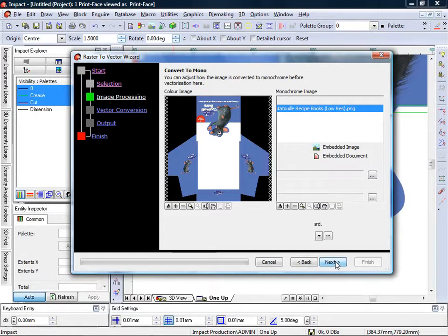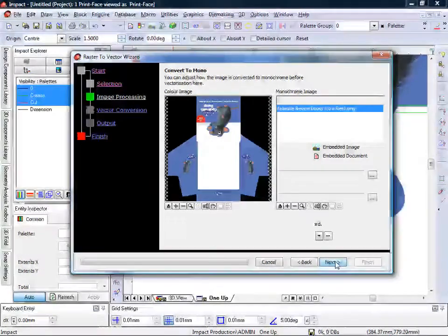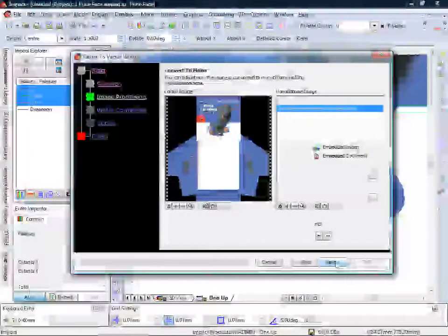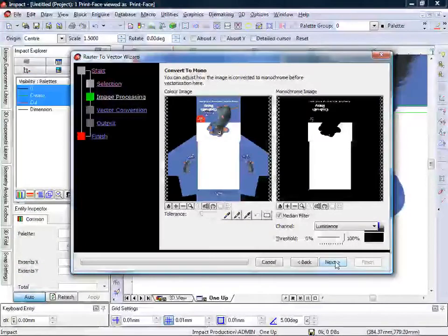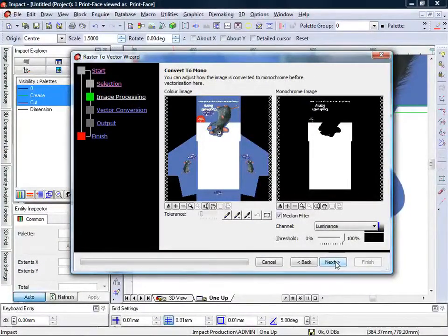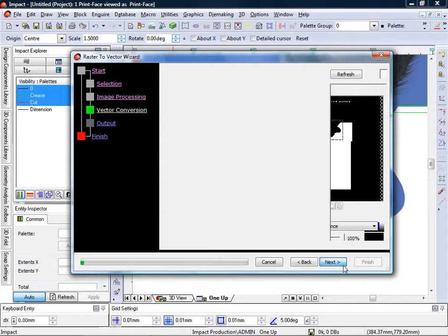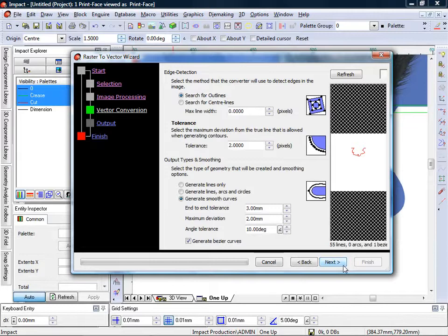I can select from a database of custom preset conversion settings that reflect the subject artwork and will produce the required result. On this occasion, the settings I've selected will convert the artwork into a silhouette. Having completed this process, I'm now going to crop into the area around the rat's head. The Autotrace wizard will use default settings to create a series of lines and arcs around the defined area, after which the user can fine-tune or rerun the feature if required.